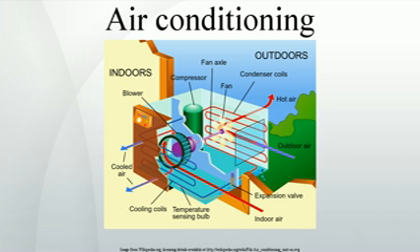These compressor-based refrigerant systems are air-cooled, meaning they use air to exchange heat, in the same way as a car or typical household air conditioner does. Such a system dehumidifies the air as it cools it. It collects water condensed from the cooled air and produces hot air which must be vented outside the cooled area. Doing so transfers heat from the air in the cooled area to the outside air. A portable split system has an indoor unit on wheels connected to an outdoor unit via flexible pipes, similar to a permanently fixed installed unit.